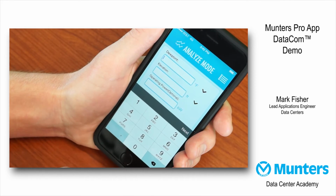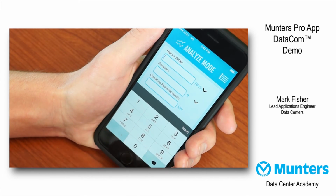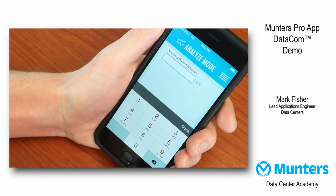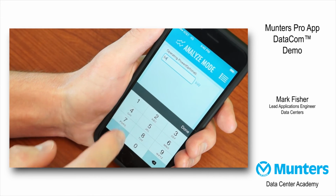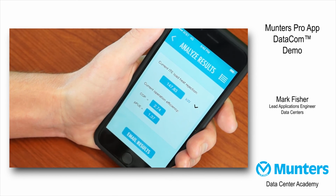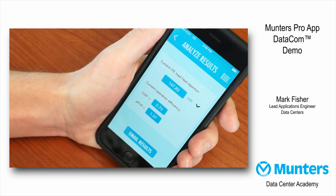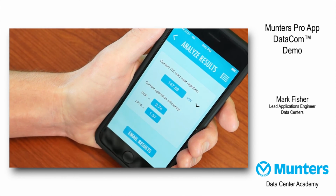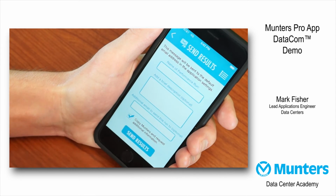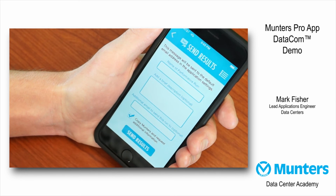And I don't have a dew point measurement, but I have a return air relative humidity of about 50, and we're at sea level, and on my power meter I measured that the unit was using about 54 kW, and I will calculate that it is rejecting currently almost 148 kilowatts of load, running at a COP of 2.74 or a partial PUE of 1.37. And similar to before, I can send these results to myself and others as desired.